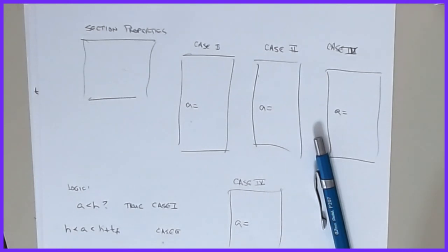So all you can see is that I went through and did my section properties that are here. Here are the dimensions that I set. I didn't even set it to an AISC shape. I just said, what's my slab thickness? What's my top flange thickness? What's my web? What's my bottom flange thickness? And so here are all the widths, here are all the thicknesses, and then I compute the A's, of course.